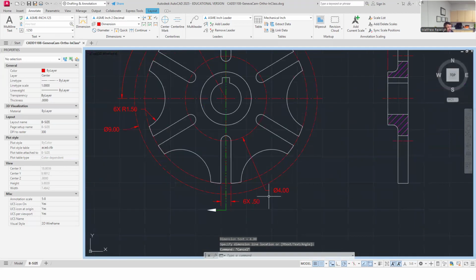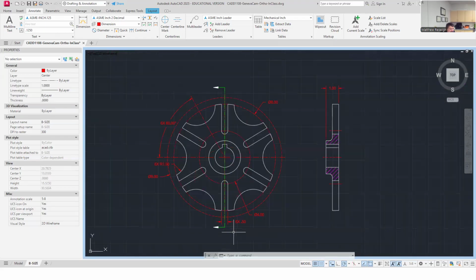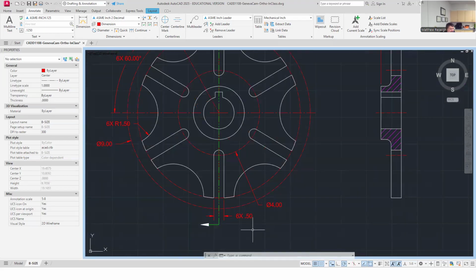These are on 4-inch circle centers. So this functions as a size and location, just like this one has functioned like a size and location, and kind of how we're locating these. This is definitely a size and location. It's this far out from center is where these kind of begin. They have this 1/2 inch wide, which includes the radius. So this is kind of like sized and located as far as I can tell, in relation to a center axis.